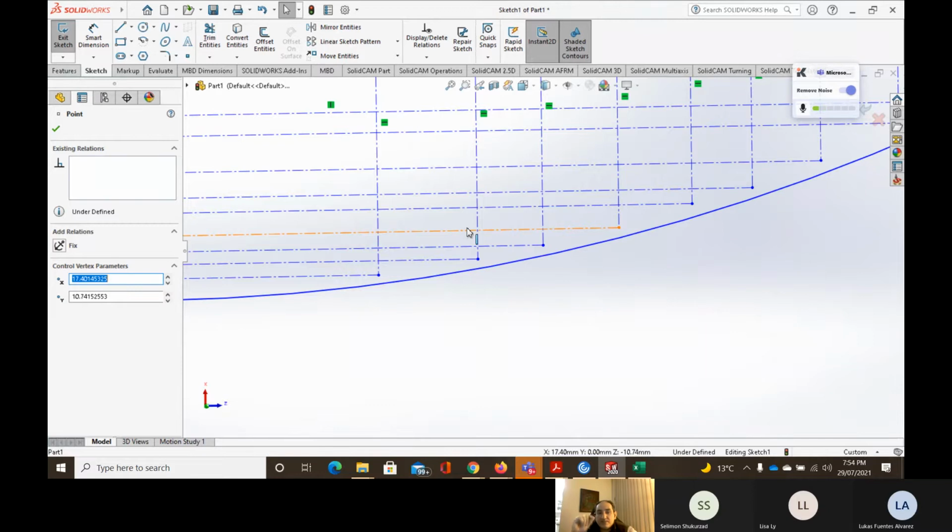Just push it a little bit up, because with the single sharp tip, the end is going to be the location of the cutting. In the rounded tip, like the carbide insert, we're going to have the radius, and out of this radius we're going to have the cut. So we always need to offset this location, which is going to be 0.5 millimeter. Usually it's not going to be a big difference.